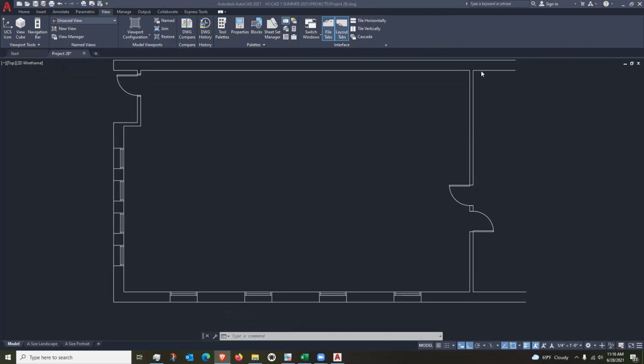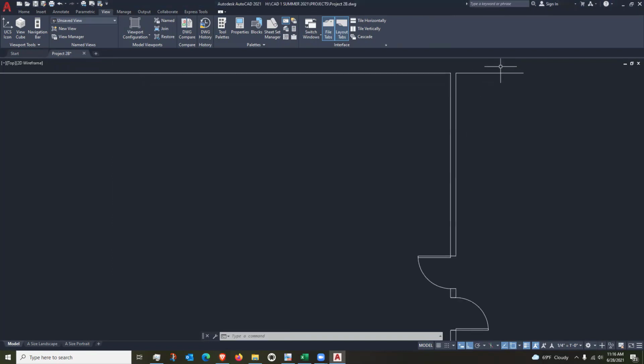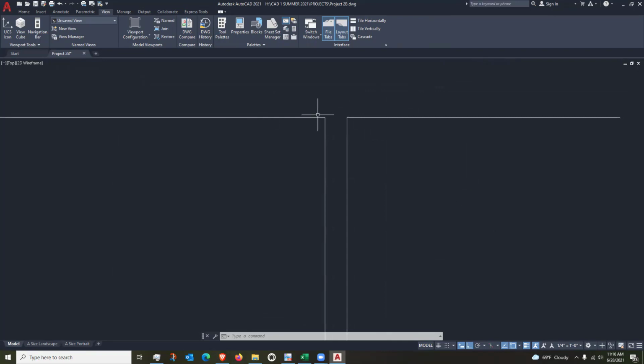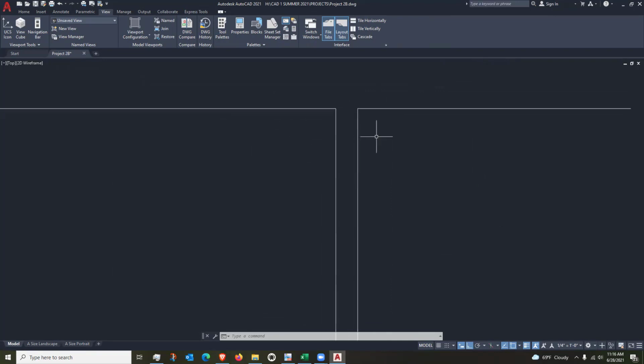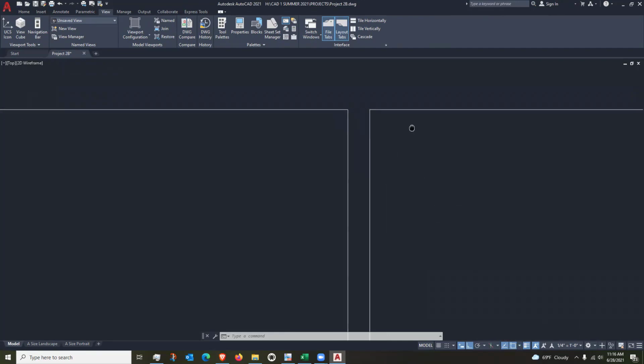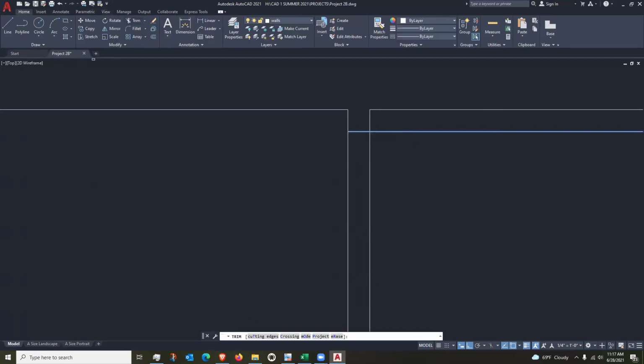So that door opening is 6 inches off this wall. Let's see, I did the offset last time. I did the snap tracking. So this time I'll do an offset. So I'll offset 6 inches. Take that piece of line and I'll extend it over. I'll do some trimming.